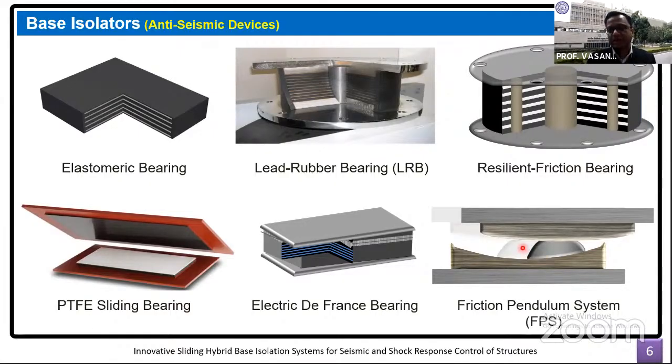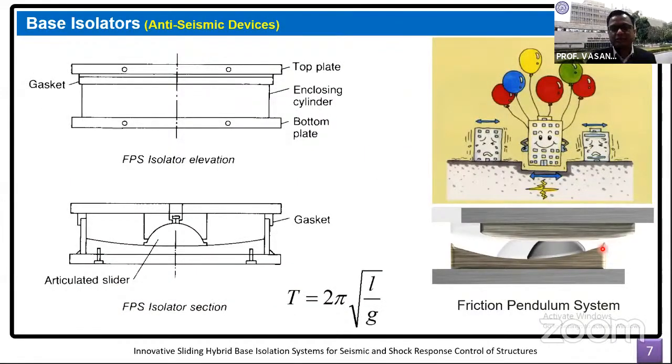On the other hand, if we make the curvature smaller, if we make it more and more flatter, the restoring capability is reduced to some extent, but it will improve the isolation capability. It will help us reduce the effect of seismic forces on the lateral load resisting elements. So again, it is the designer who would decide what should be the curvature of this pendulum system. That curvature will decide what the frequency or time period of the structure being designed is, particularly in the first mode.